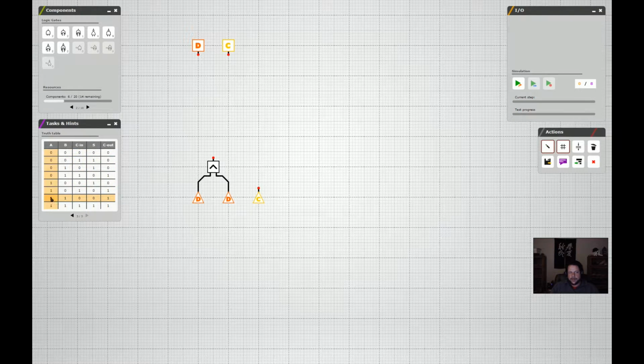And then finally, on this one, we've got two 1s, so the output for the XOR is a 0, and Cn is a 0, and the output is a 0. Again, the result of an XOR would work for that. And then here, 1 and 1, so the output would be 1, combined with Cn 1, XORed together would give us a 1.